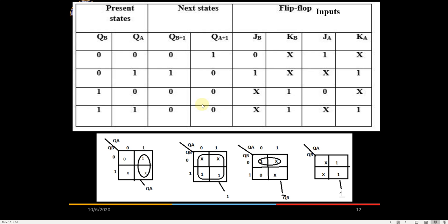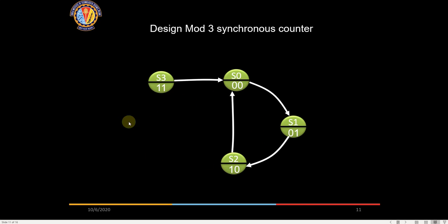Here you should have all the variables. Suppose it is an 8 variable thing you are making, and you are making a 5-bit counter. So three of these states will be useless, right? They may never come, but you should cater for them also, and try to put them into one of the states, so that if for any reason the flip-flop is stuck in any other outputs, it will come into the loop. So not necessarily you should get it into 0 0.